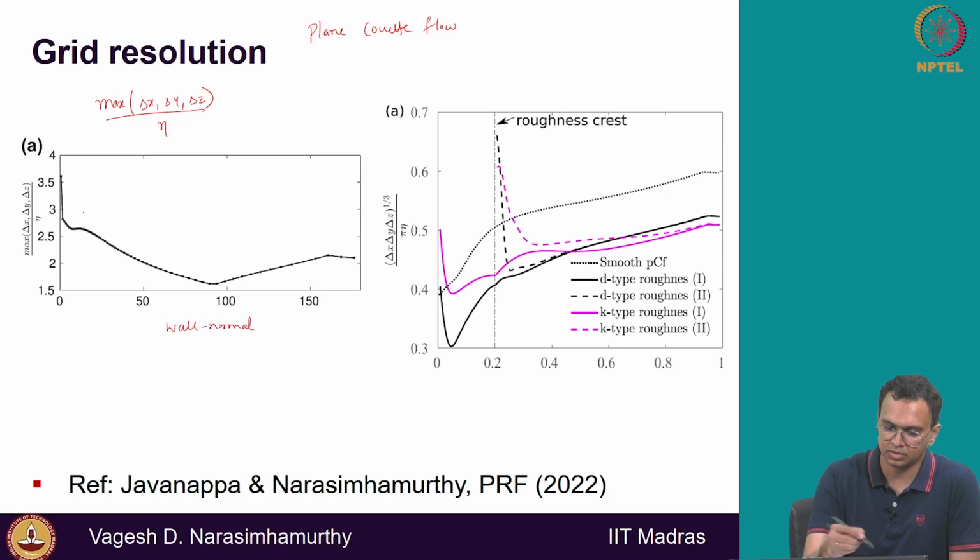So I'm just plotting here. Now you can see that it is not equal to eta. The mesh size here, the max of this, is going like 3.5, 4 or something. So this is also acceptable. So this is the delta by eta, right? Delta by eta is now of the same order of magnitude, comparable, same order of magnitude, which is acceptable.